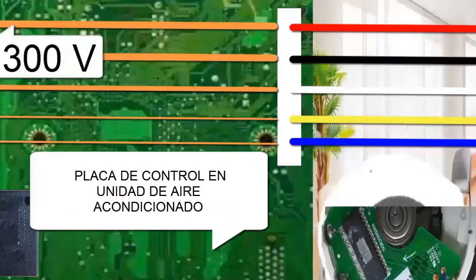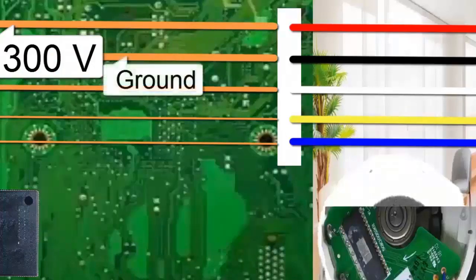The indoor unit fans have the electronic board inside the fan. They generally have 5 connection wires with the electronic board. Red high voltage power wire, usually 300 volts. Black ground wire with 0 volts. White power wire to the electronic controller inside the fan, usually 15 volts.